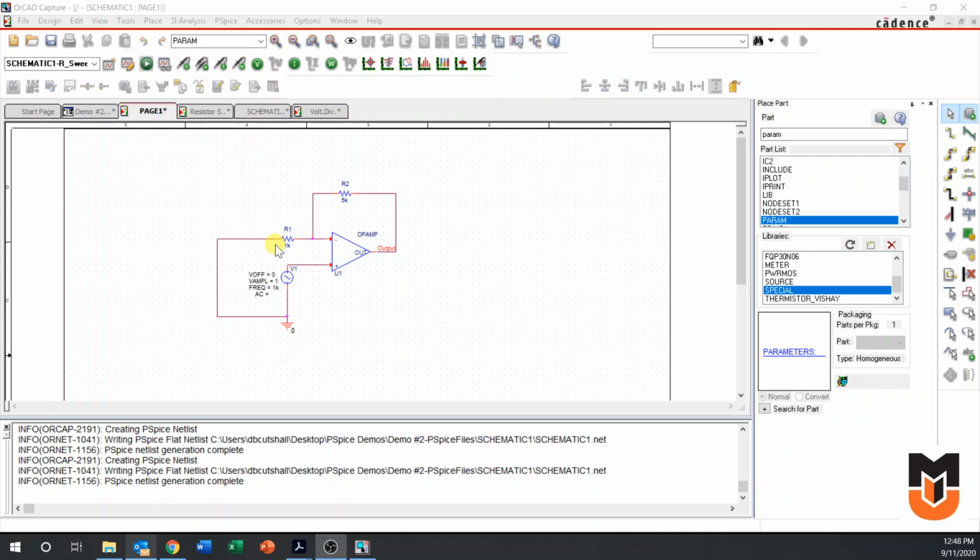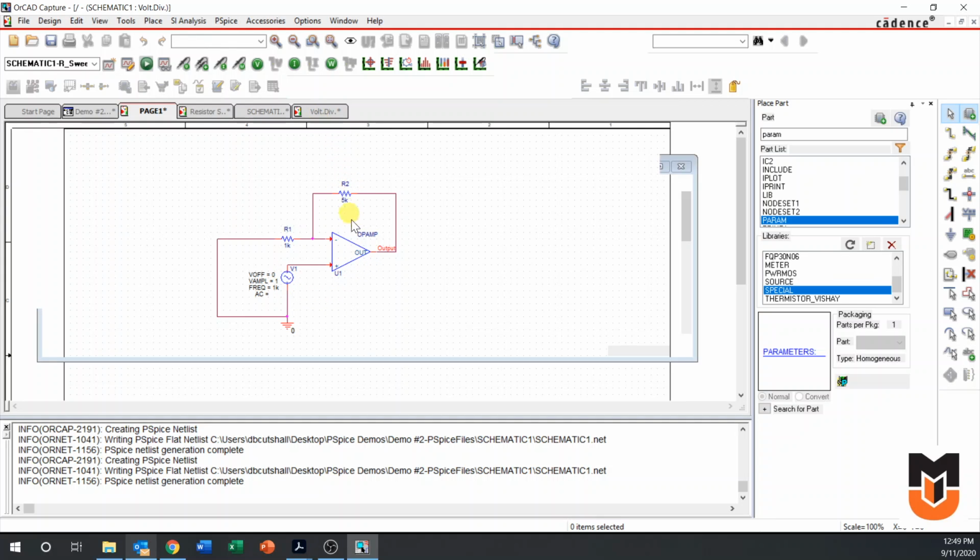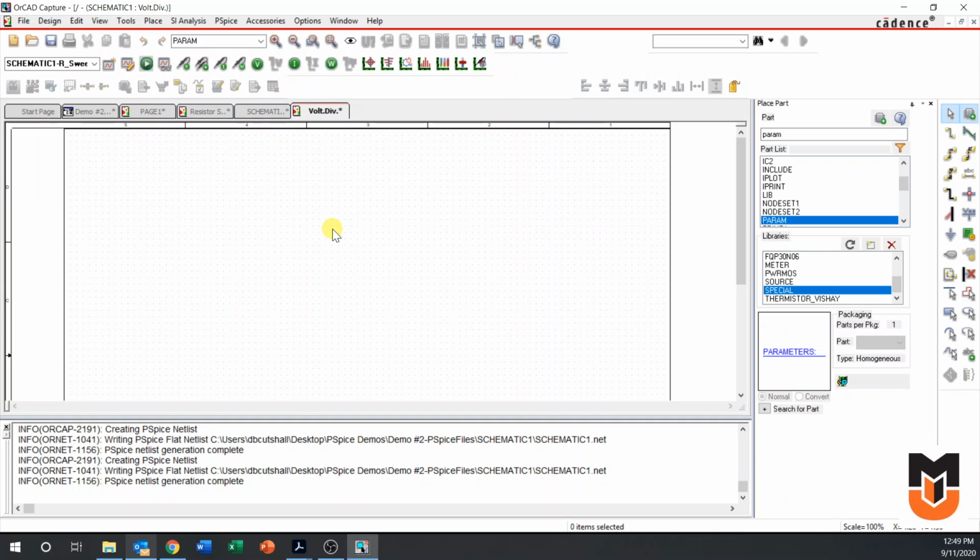Due to a limited amount of power supplies in the lab, we're not going to have enough to have 3 power supplies for each station. So one way that we can get around this is we can use the same power supplies that we're using here, one or the other, and we can use a voltage divider network in order to create the input voltage from that supply. So let's look at what that's going to look like here with a simple voltage divider network.